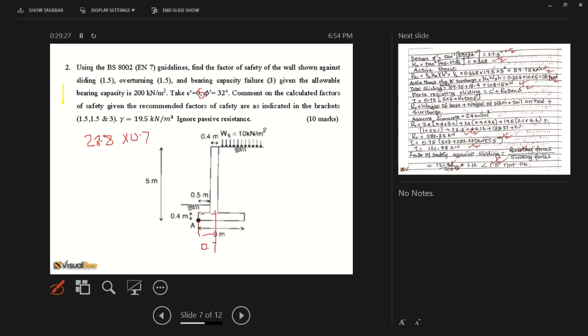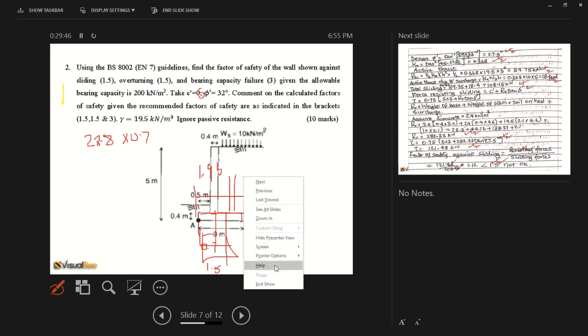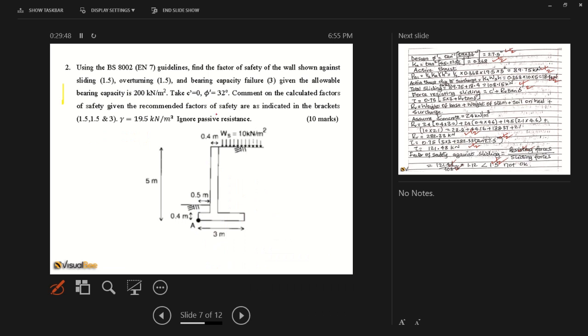And you can do the same for this part, whose distance to the center is 1.5, and these other ones, the distance is, I think, 1.95 for all of them. Also, something I needed to explain is that the place where we're taking moments is point A, but actually you can take it even here, as long as you're consistent. So the distance will change a little bit, but even if you take from here, it should be fine.